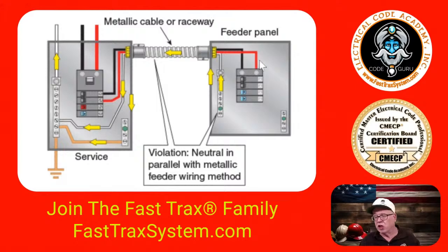Now, could this be liquid tight flexible metal conduit and this be a 60 amp remote panel? Maybe. And if that's the case, if you meet all those length limitations and follow those rules, then maybe you can get away from that. But other than that, you're going to be very limited in the application. Okay? So that was the whole purpose of the illustration, not just to talk about the objectionable current, not just to talk about the improper case to neutral, but also what are your recommendations for fixing it?